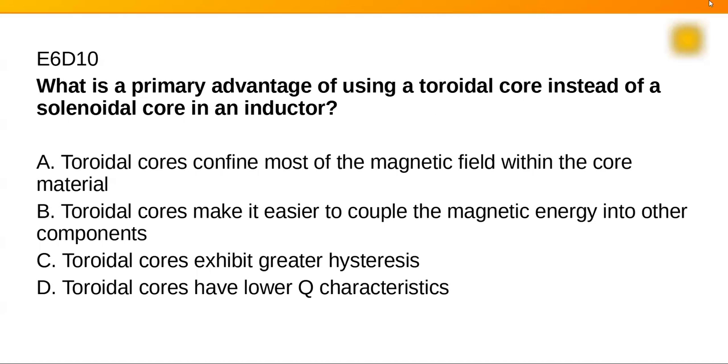I'm not meaning to deviate too much here, but Clyde did a class about common mode chokes. Right. That's what we're talking about. And he said those coils of wire were almost useless. Well, you're going to need a lot of large diameter, a lot of turns in order to come up to the equivalent of having a toroid with multiple turns.